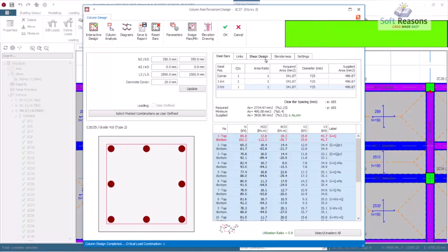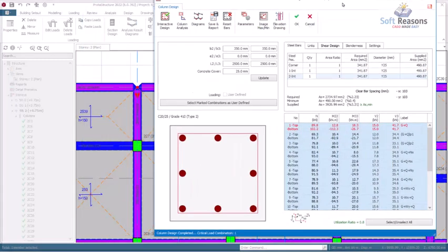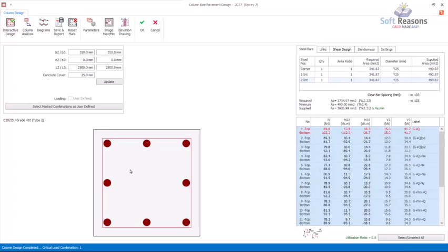And at this point, because it is at cantilever beams, you may not necessarily be able to change these sections as flexibly as you can change the sections at the first floor. All right, you may not be able to change the sections. If you want to actually increase the sections, you may increase it along the beam directions.